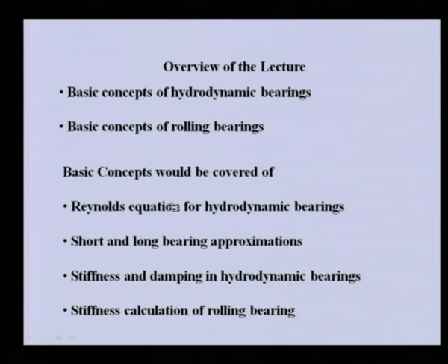For the bearing, we will introduce the Reynolds equation for the hydrodynamic bearing, and for the short bearing approximation or long bearing approximation, we will see how we can solve this particular partial differential equation in closed form. We will also give a brief idea about how, if the bearing is finite, the Reynolds equation can be solved using the finite difference method.